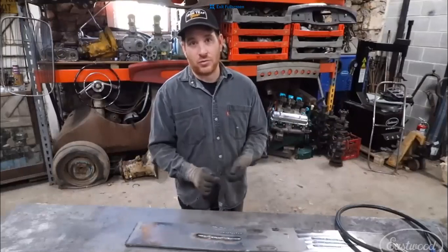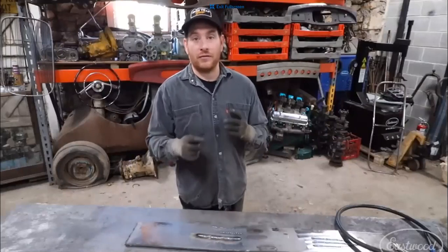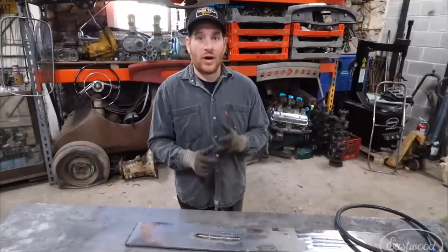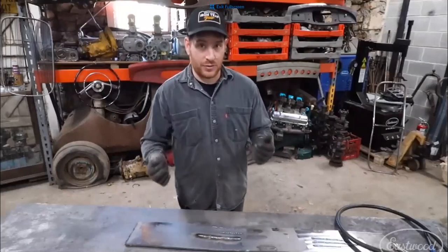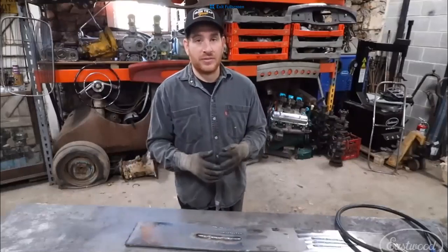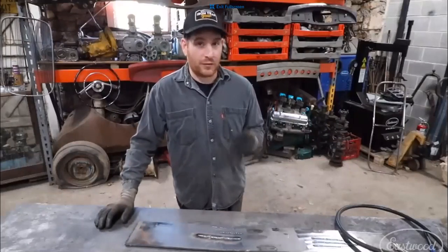Getting a good MIG weld consists of mostly technique with the actual welding process, and more importantly, the settings on your machine, where you're blending the voltage or heat with wire speed, or the rate that the wire is coming out of the tip of your MIG gun. So when you blend the two of them together, you should get a really good, even weld that's going to sound like frying bacon.